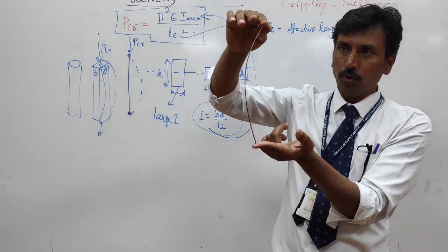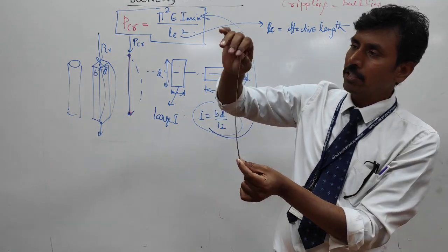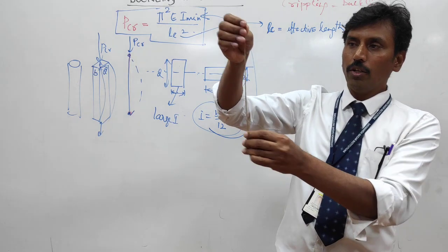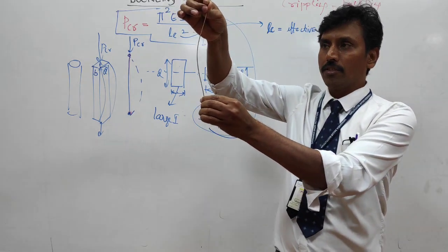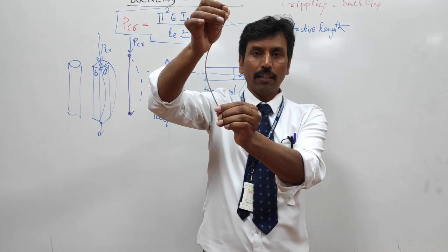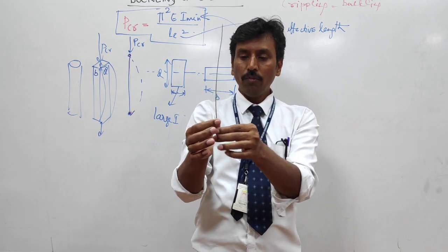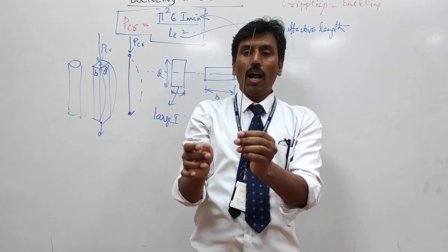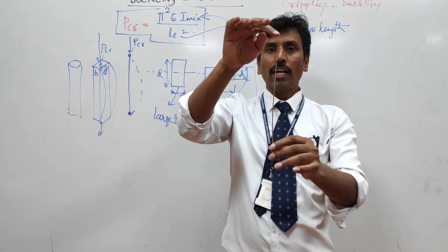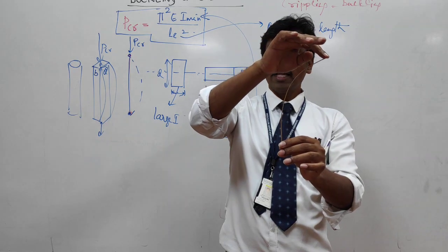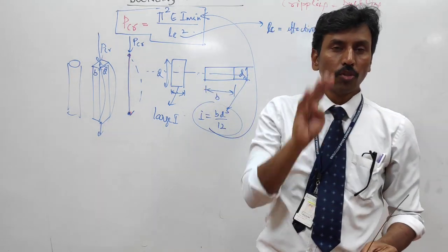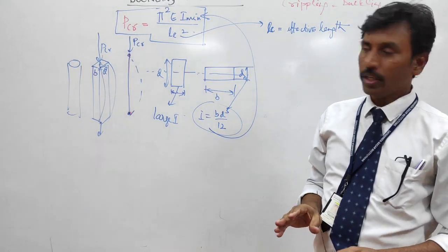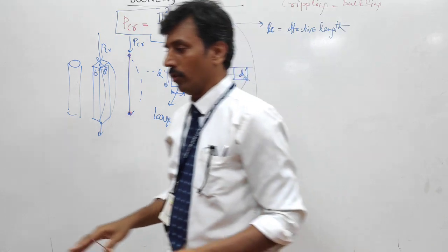So I am applying a force. It is like a hinge, which means this end can rotate about itself. The other is holding it tightly like this. And another is holding one end like this and the other like a hinge. And one is holding it tightly like this, and the other end is free to move in any direction. It bends like this. There are four ways, and for these four ways the values of LE that you substitute are different. So you should know these four values.